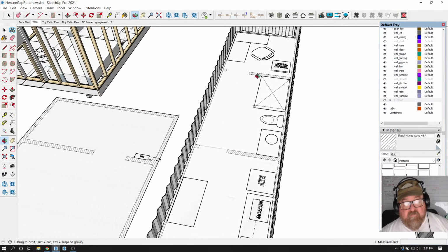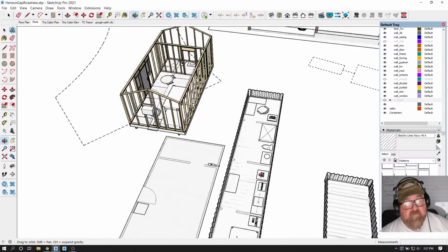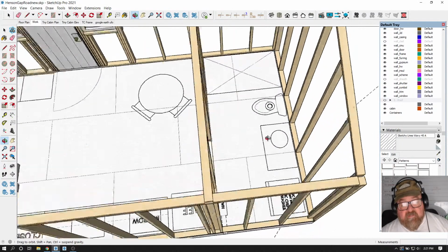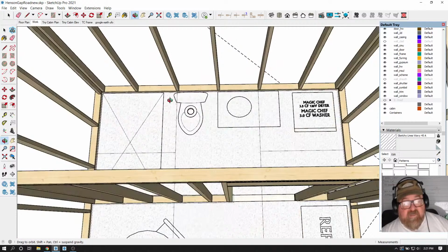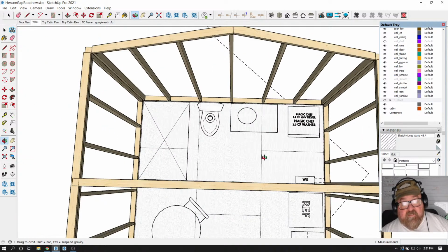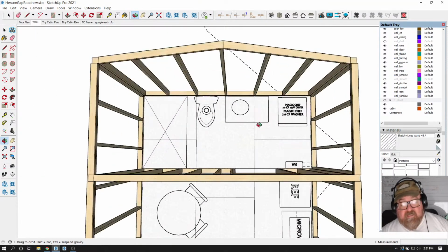But this bathroom would have to be in a linear configuration like this. Where you saw a typical bathroom layout, the 5-foot shower makes the width of the bathroom. This is your typical 99% spec house bathroom layout where you have a 5-foot tub shower. This is a walk-in shower. Then you have your toilet and your vanity. And normally the wall would be right here, but I'm taking advantage of the 12-foot width and I'm putting my washer dryer there, and I'll have a little water heater on the wall there. See, this is a nice size bathroom.